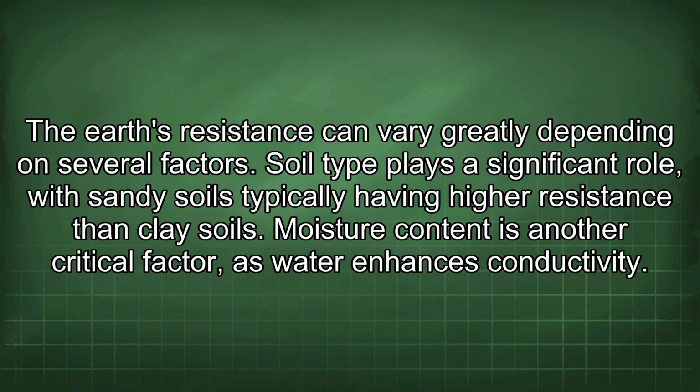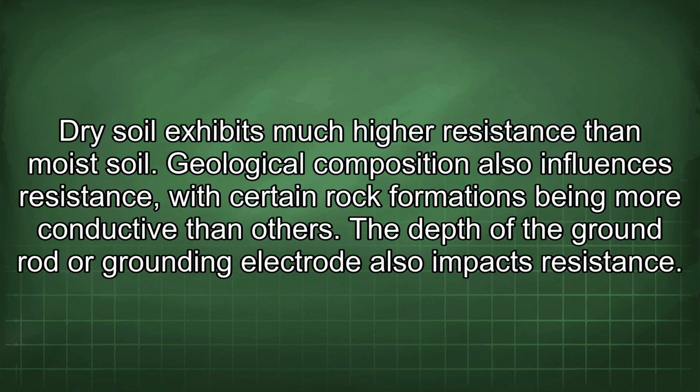The Earth's resistance can vary greatly depending on several factors. Soil type plays a significant role, with sandy soils typically having higher resistance than clay soils. Moisture content is another critical factor, as water enhances conductivity. Dry soil exhibits much higher resistance than moist soil. Geological composition also influences resistance, with certain rock formations being more conductive than others.